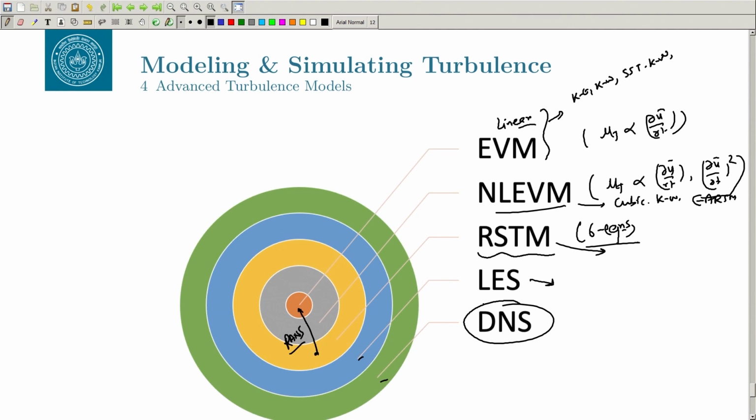So, this ends the discussion about the Reynolds averaged Navier-Stokes equations, or RANS equations, turbulence modeling, and I took some time to discuss the RANS, because this is the model that we will be using the most. Unless you are in academia, the chances of using DNS are not very high. LES is now becoming a tool for industries for some problems, but still it is not mainstream. You will not be using LES for your regular design tool, or if you want to do a parametric study. So, in most cases you will be using your RANS model, despite the limitations of these models that we talked about.